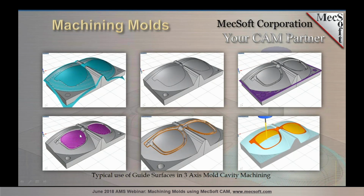And there's a guide surface on that island top that is the same surface as what's in the model, except that it extends a little bit past the parting line. And we'll show you why in just a moment. And then in the bottom middle, this is the one I showed you in the previous slide, where we showed a guide surface extending up vertically from the cavity. This is what it looks like along the entire cavity parting line.